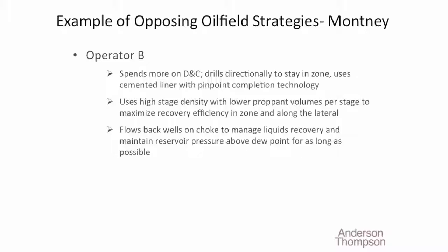And the wells are flowed back on choke to manage liquids recovery and maintain reservoir pressure above dew point. This is a liquids-rich area, so that's critical as well. For long-term liquids recovery, you don't necessarily want to flow back to an open choke. You might drop below dew point and leave a lot of those condensates and liquids behind.